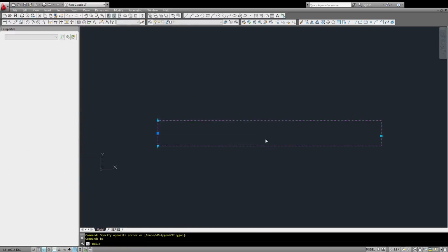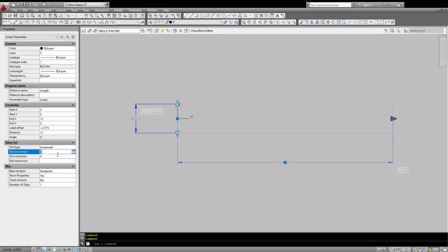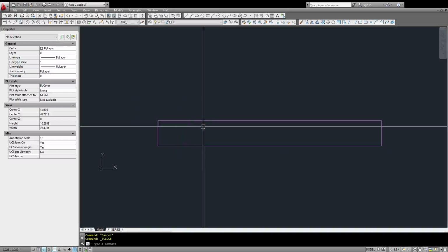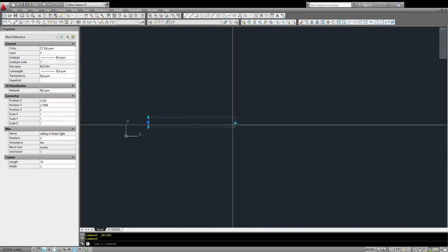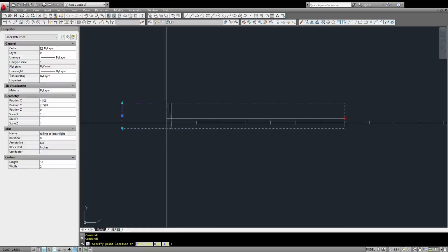And from here you have the option to have increments or something. Distance type, if you're doing a linear light, there are increments like 1.5 inch increments, like 2 inch increments, minimum of like say 4 inch. You cannot go down that length, 4 inch. You can assign those things also. So let's save. So it shows you those increments. You cannot go down that 4 inch anymore.